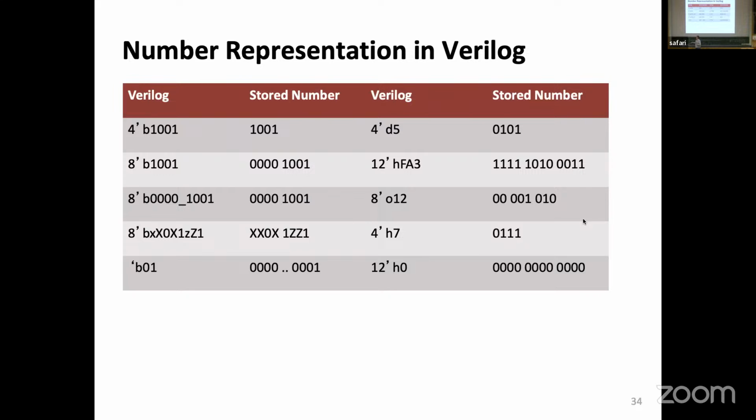What size is this? It's not necessarily, because on a 32-bit machine, like Intel, Pentium, whatever, you are using this, but you could be designing a 64-bit processor. So for the design, you think you're using 64 bits, but because you're compiling it on a 32-bit machine, it's assigning strange things. So it also should help you identify what people are doing. There's a lot of things you can do in Verilog and SystemVerilog that don't make any sense. Still, it will not complain. That's why didactically it's a little bit annoying.